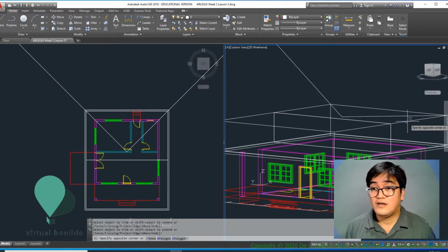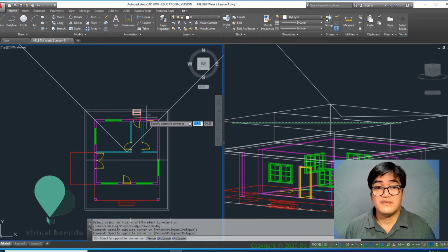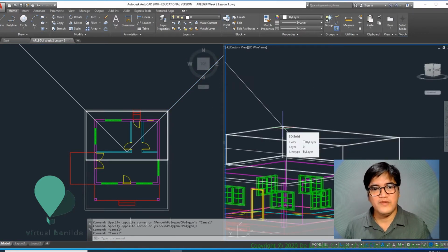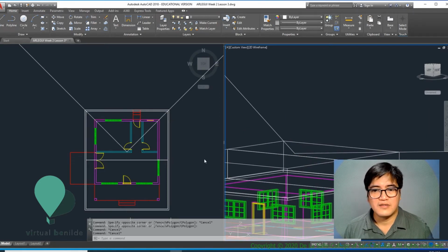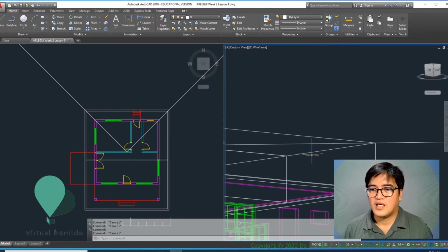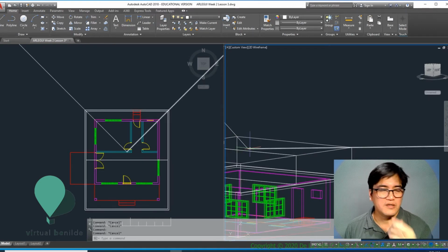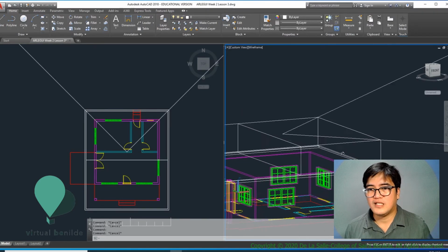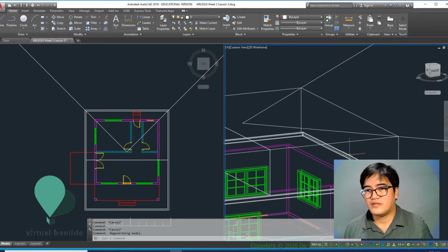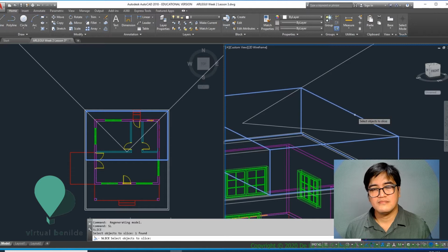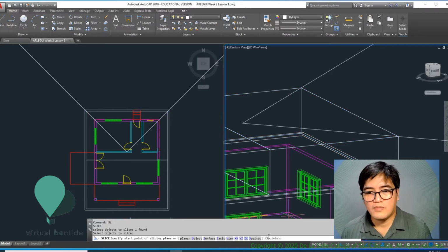So we have this solid object, and we have these line references. I'm going to slice it to sculpt the gable roofing. A pretty good idea where things are. So it generated for me the midpoint of where the gable is going to pitch. There's the pitch here. I'm going to slice over by using a 3-point method. So here I'm just going to rotate this, and for me to explain better, I'm going to slice this object. Again, invoking the slice command, SL. I'm going to choose this, enter once. Now I'm going to choose 3 points as my option.